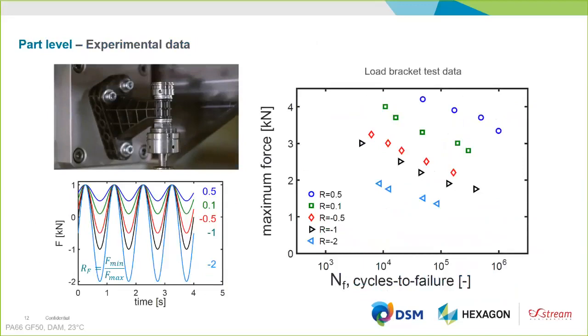It's also good to see the 3 bolts, which fix the part to this steel base plate. And already with tightening the bolts, we apply some stress into the part as well. And we also take that along in our simulation, so that stresses that are in the part before we load it in fatigue are also included in the analysis.